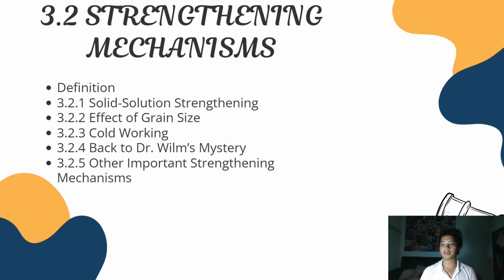Three distinct processes can occur during annealing. Annealing is often employed as an intermediate step in the cold working process to reduce the internal stresses in the material and increase its ductility, so that it can undergo further cold working without introducing microscopic defects such as cracks. Three distinct processes can occur.